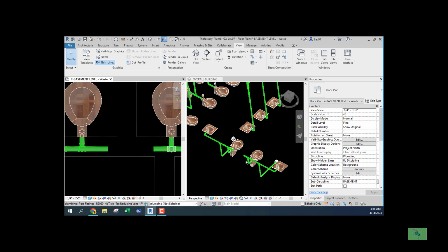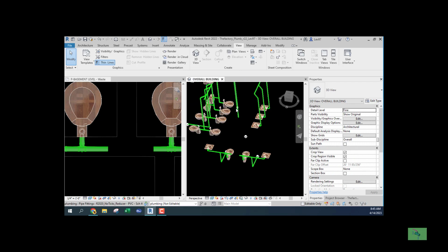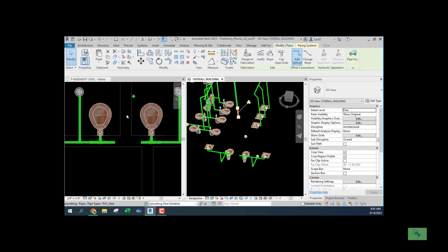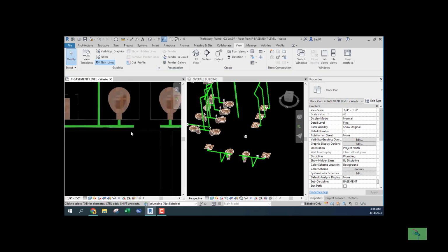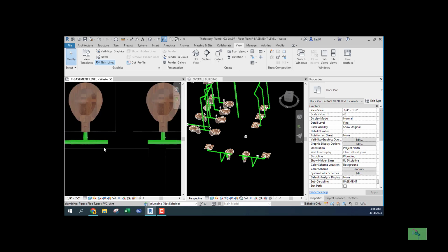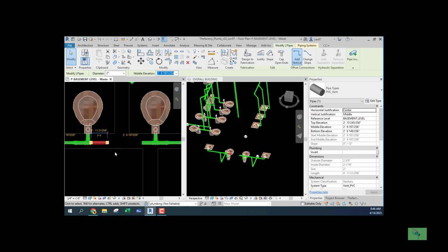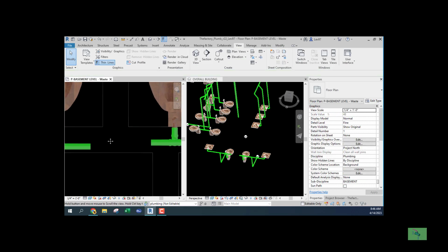So now we need to connect these two, and from there we are going to connect into this riser. Now, how do we do that? That riser is this riser in plan view. So what I need to do now is make sure that these two pipes are in line with each other. Okay. So let's go extreme first. So make this out just a little bit and then align it, to make sure that I'm aligning right.